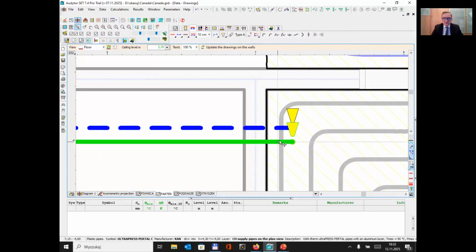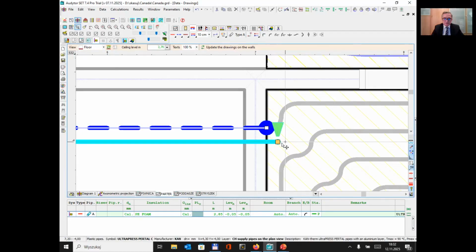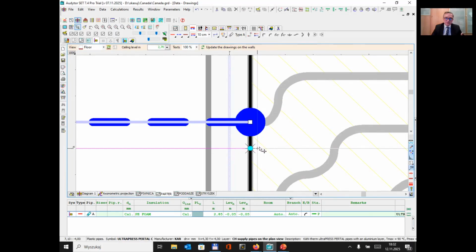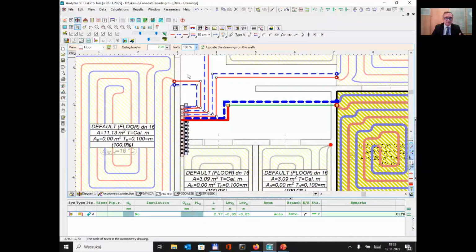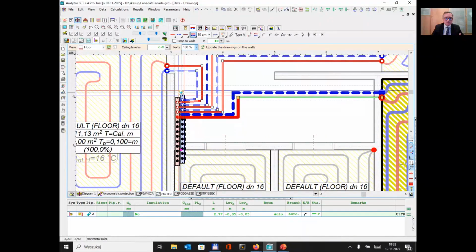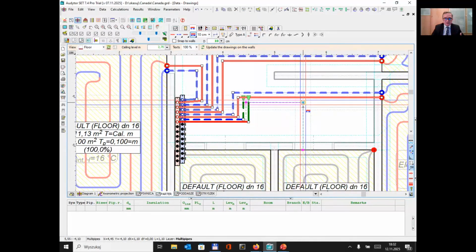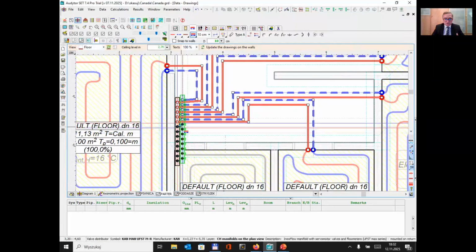Oh, here I have clicked in a slightly wrong way. I should click at the border, but I can move these points. So when you see the exclamation mark, it means that the pipe is not connected to anything. And now it's connected correctly. So still 2. I can purposely go not the shortest way, because I would like to use these connection pipes also as heating pipes.